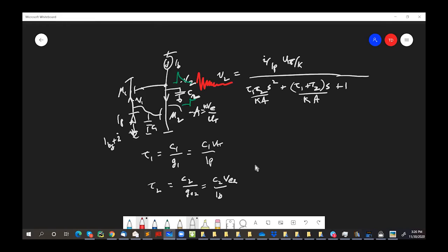So Q is like, think of it like a clock or a pendulum. You want a high Q. If you have a crystal with a very high Q, like a crystal oscillator, that means it's a high quality crystal, like a high quality bell. It keeps ringing for a long time. Usually you may want that if you have an oscillator. You may not want a high Q if you really want to guarantee stability.